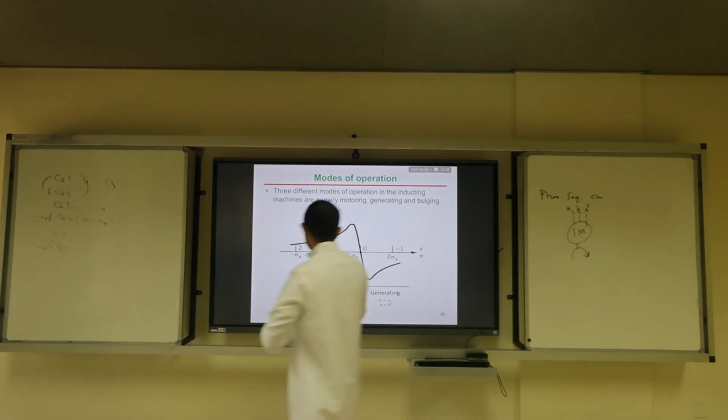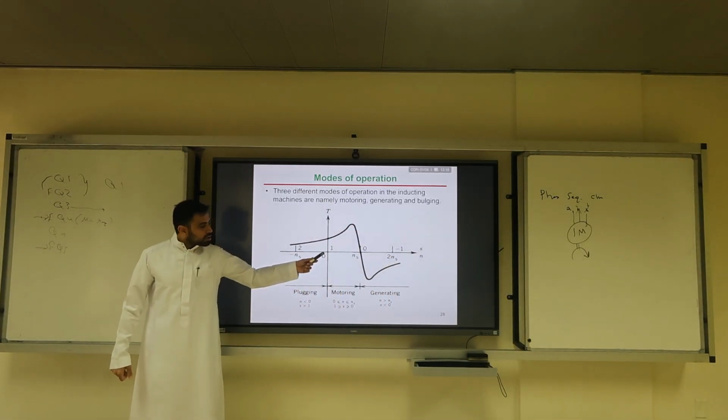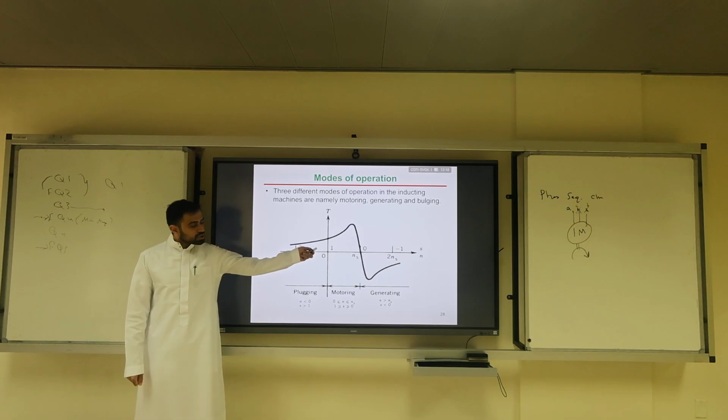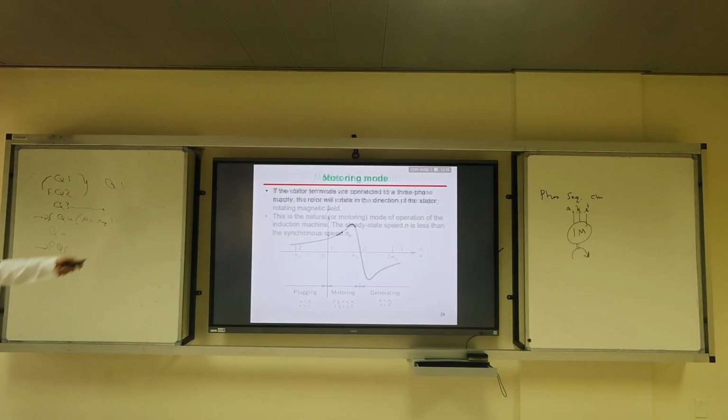So in the plugging, if you want sudden braking, the best way is just to change the phase sequence. And this might be a question in the test, okay? So let's explore what we just discussed.